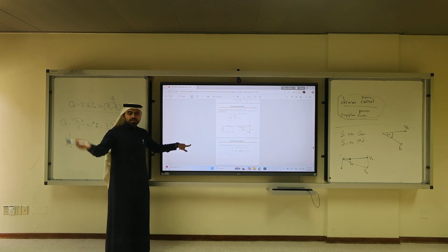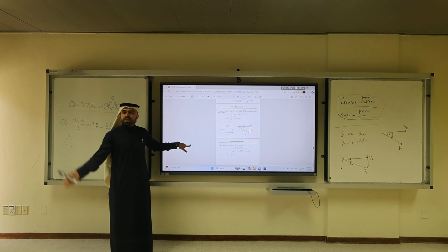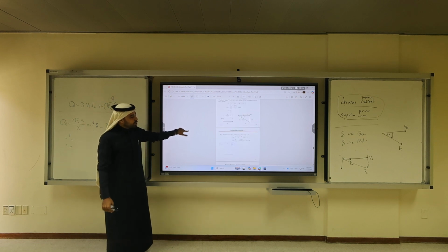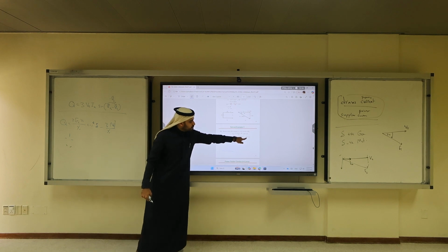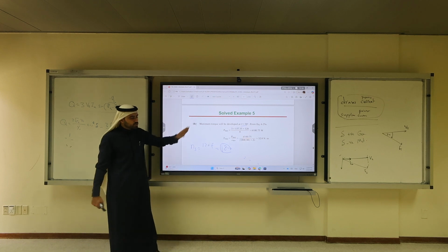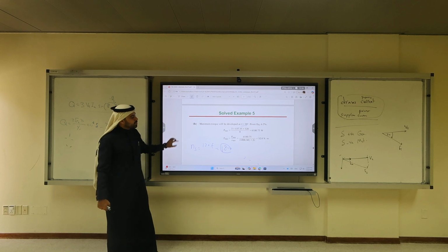I would say 80%. You can be 80% close to that. Never go to 90. So the torque, 32.8 newton meters, we should not actually have it. Maybe we should reach up to 28 and then stop. Because at 32.8 we would lose synchronism.